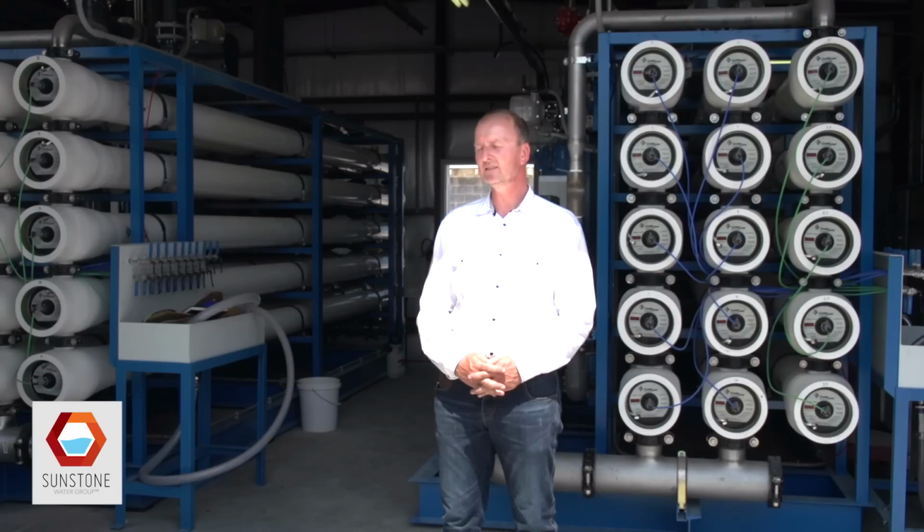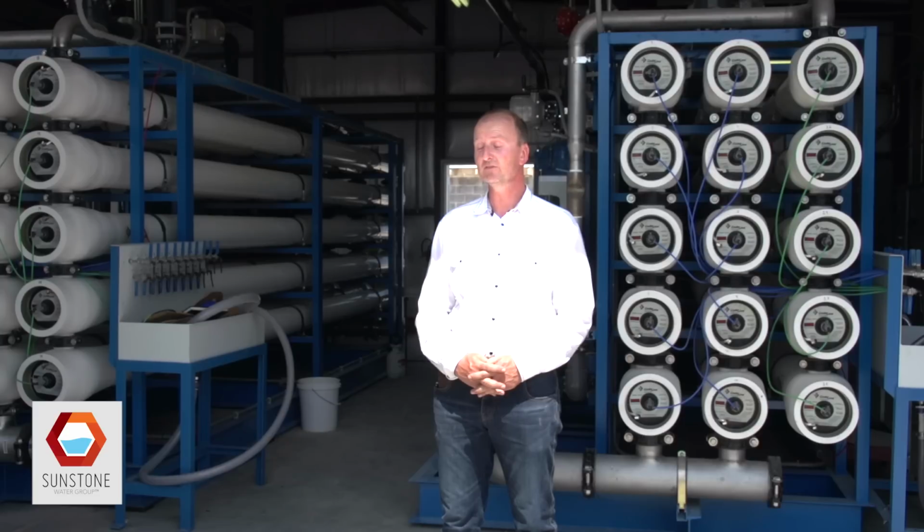Every time you have at least a small amount of fouling of the membrane, the energy cost goes up because of the higher pressure drop. And this side here actually spent more than 65% of the operating costs just to maintain these membranes. That's a lot. And that's something we need to do something about. Our system out here is very flexible, and we have a climate control container because it is very hot here. But we will now show you how it works when you foul a membrane.